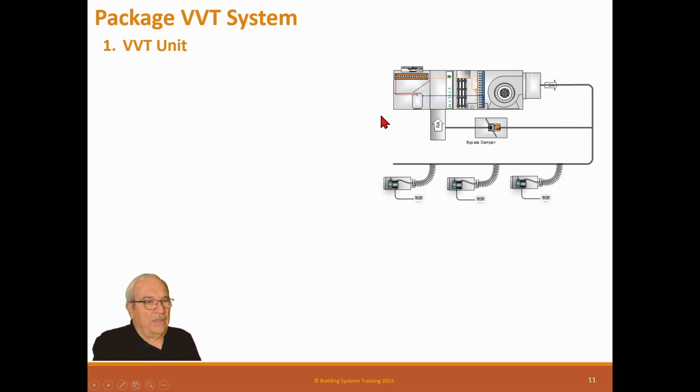There's only one little issue with this system. This system is capable of heating and cooling, because it's a package unit, right? You can put strip heaters down here, but normally we don't do that. Normally these are cooling only valves. So what happens is we have these space sensors out here. They're communicating with the controller on this unit. It says it's getting cold, we need some heat. Our dampers are down at minimum flow, so we need some heat. Well, this unit switches to heat. Well, the problem is these boxes now have to become heating boxes. They were cooling boxes. Now they're heating boxes, which means their polarity must change.